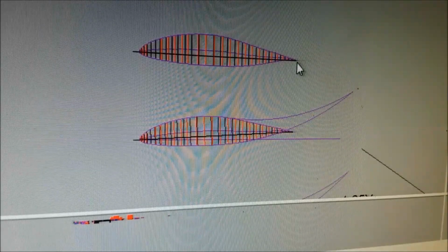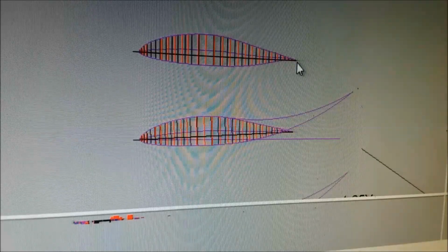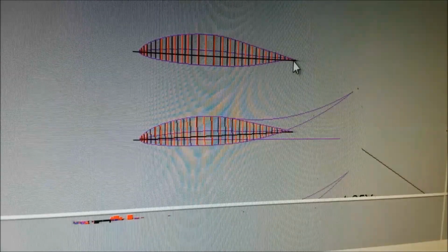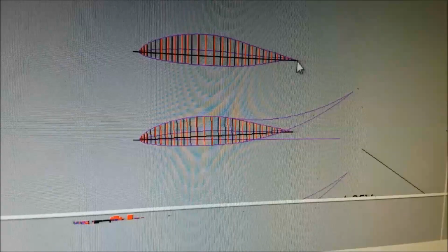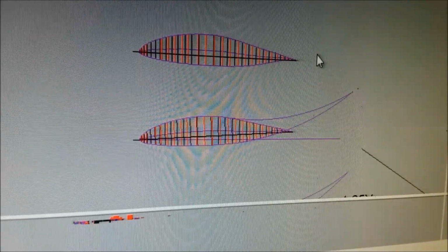utility knife, drywall knife. Cuts really easy. Cuts through the glass and the resin. Gives you a really clean edge. And when you do the second, when you turn it up and you cut that on that same green edge, and then very little sanding to make an absolutely straight line. Okay.